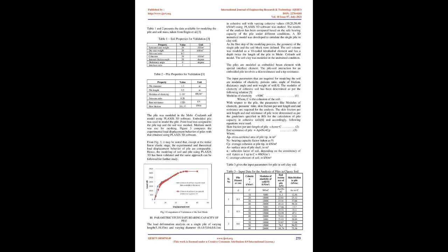2. Model validation. A validation of soil model. The Alzey bridge pile load test is an axially loaded validation case, which is widely used by researchers for validating new soil models. The Alzey bridge pile load test was carried out near Frankfurt. During the test, load cells were installed at the foot of the pile to measure the loads that are carried directly by the pile base. The test results and other parameters are presented by Englert et al. The test considers an axially loaded pile with a diameter of 1.3 m and a length of 9.5 m. The groundwater table is approximately 3.5 m below the ground surface.